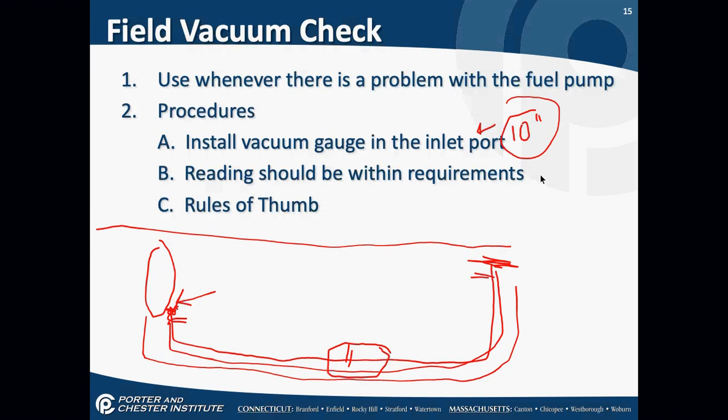Now, why was the service technician liable? Even forget about the point he wrote on the ticket. He'd been out there 6 times. Why was he liable? He could have replaced the compressor fitting. Well, he couldn't see it, but what could he have done that we teach at any school, even the apprenticeship system teaches every single student that goes through the school? What did we just talk about? Guys, the vacuum checks.